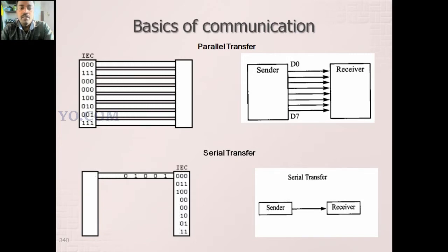Similarly, consider the decorative lights, the LED lights. Each LED is connected in serial manner. Every LED can glow at 3 volts, but a group of LEDs connected in serial manner can take 230 volts, with some current limiting resistor. So that is serial lights.